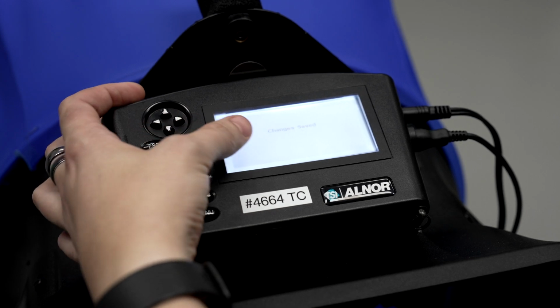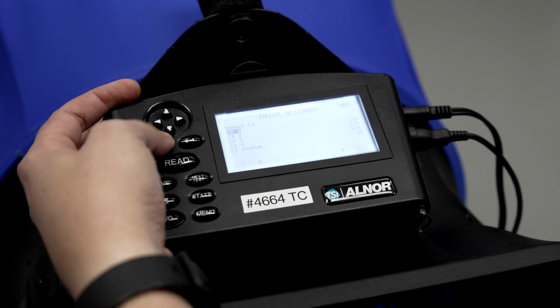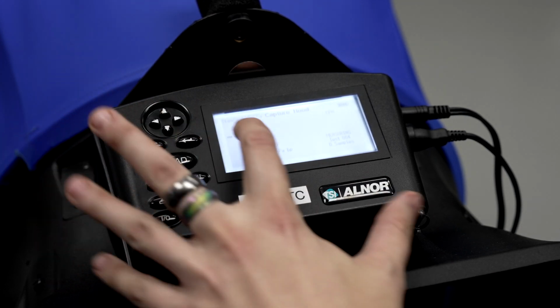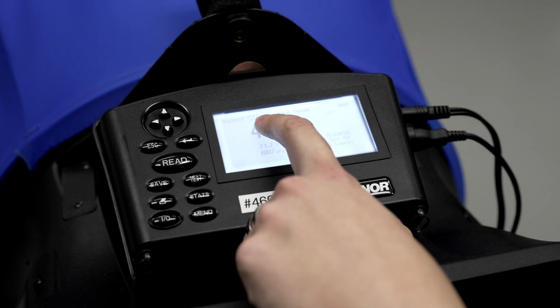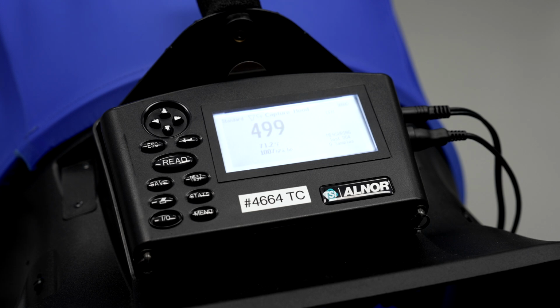And once those changes are saved, we'll navigate back to the base menu, and we'll see that our value of the flow hood now shows the CF to signal that it is a corrected value, and our flow is in agreement with our hardware. We're at 500 CFM across all of our traverse, our unit, and our flow hood.